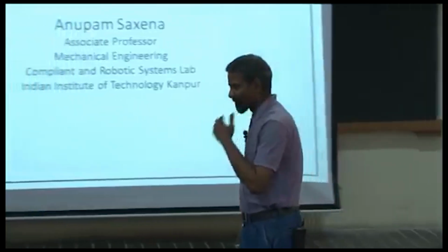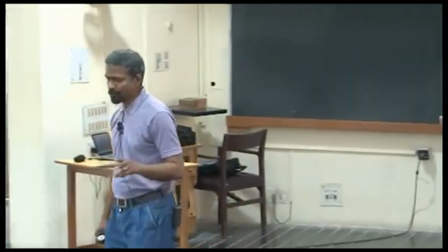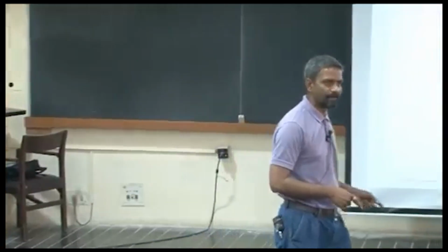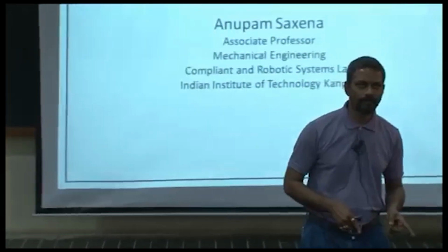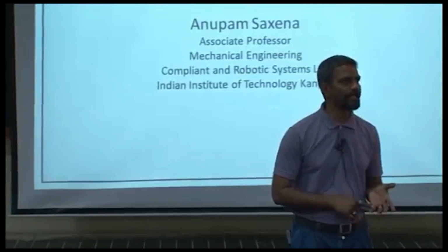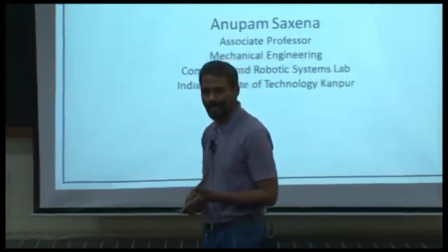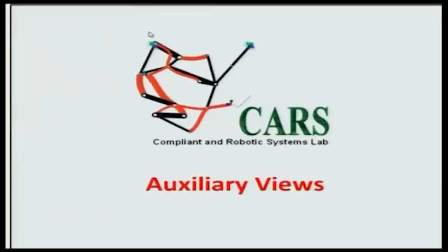I would briefly explain the cutting plane method. And there was a little bit of confusion. In fact, there was quite a bit of confusion with regard to how to determine the visibility using the cutting plane method. I would actually tell you not to worry about that. So find the intersection between the two planes using the cutting plane method, and then use the projection method to figure out the visibility. So I'll talk about that.